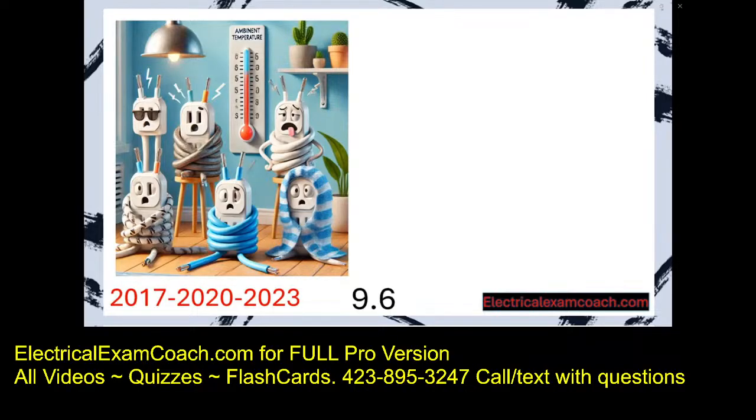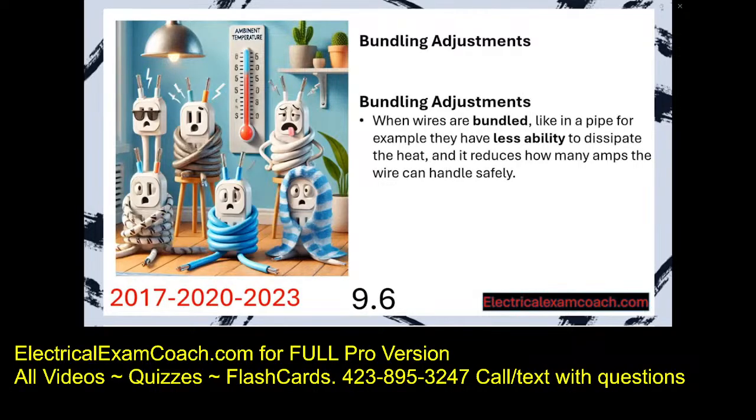In our previous lesson, we learned all about bundling adjustments and how to derate them when wires are bundled inside of a pipe, cable, or raceway. In this lesson, we're going to be learning about ambient temperature corrections. It's very similar. We just pull from a different table, but it's the same style demand factor process that we've been doing this entire program.